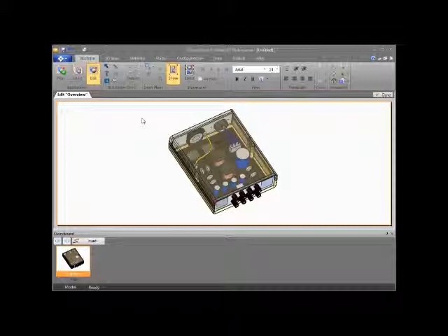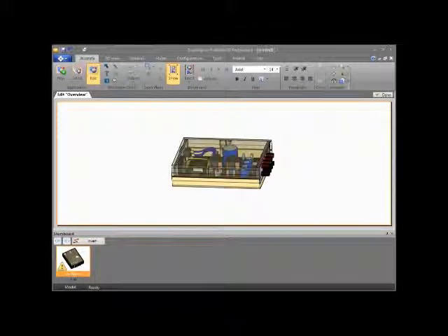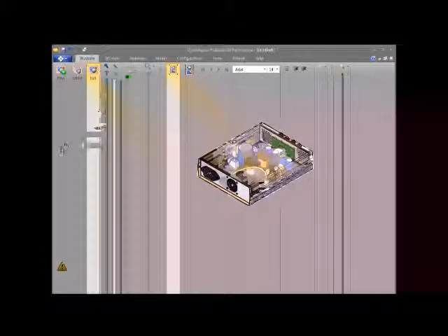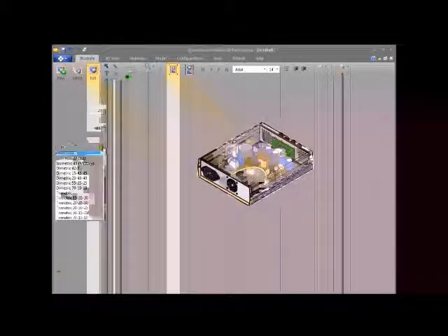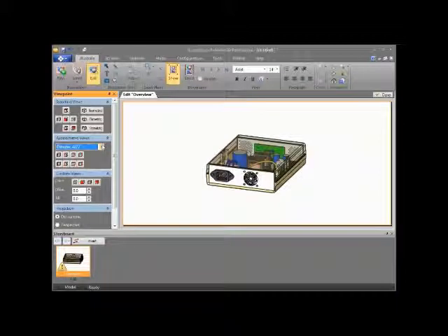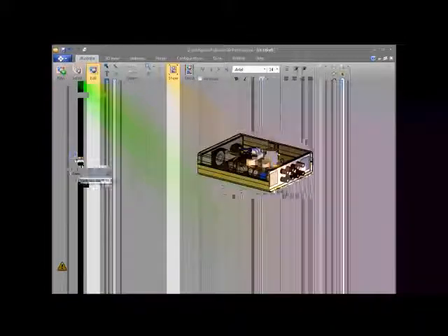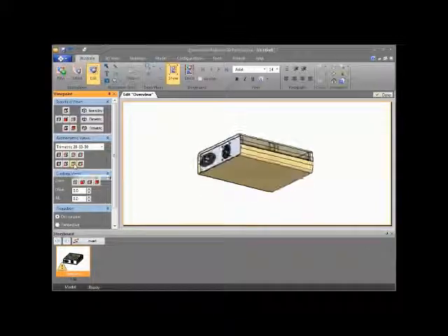So some of the ways that you can orient the model, there's this viewpoint panel. I can click this Extended Group Properties button here, brings up my viewpoint panel. And from here we have the standards, like your isometrics. But there's also a whole library of axonometric views here. So I have different dimetric views to select, different trimetrics. All of these are industry standards, and all of them have the very crisp, straight up and down lines built into them. And not only can you just take and look at it from a normal view, you can use any of these 8 viewpoints to orient the model precisely.